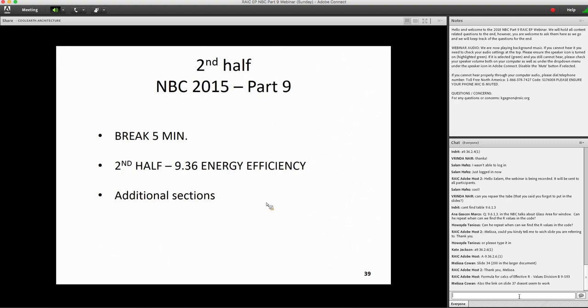Okay, and to recap, RSI is what? It's the thermal... It's like a factor that tells you the thermal resistance. So I think it would be thickness divided by the conductivity. So a higher one has a higher thermal resistance number.